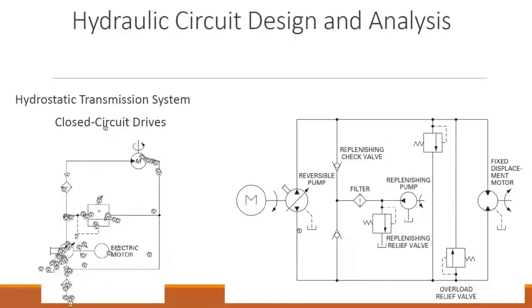After some time, there might be some leakages developed in the whole circuit, or some recesses produced in the pipelines or maybe in the pump. The oil that is lost from this is taken by the pump from the tank.